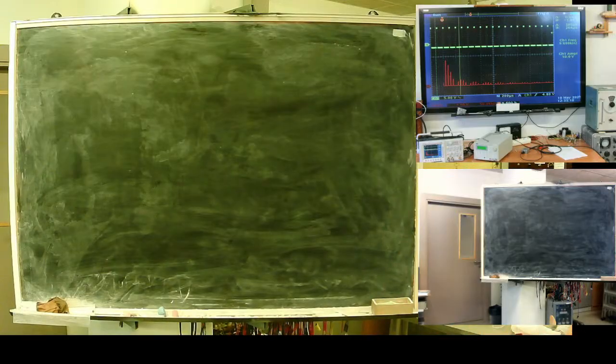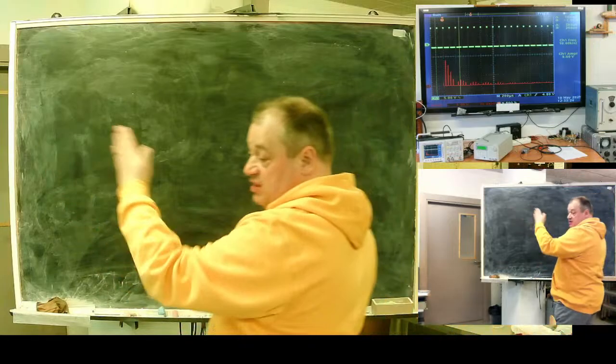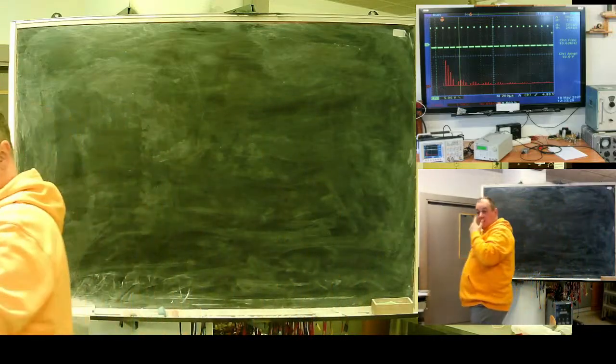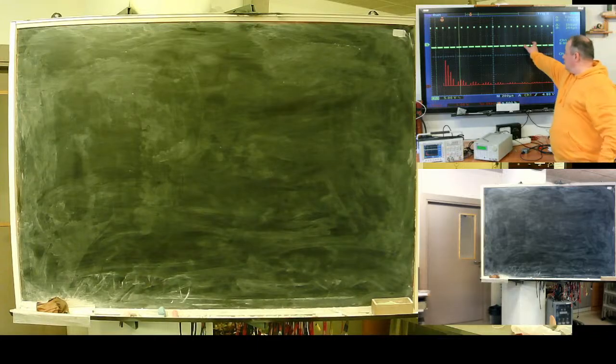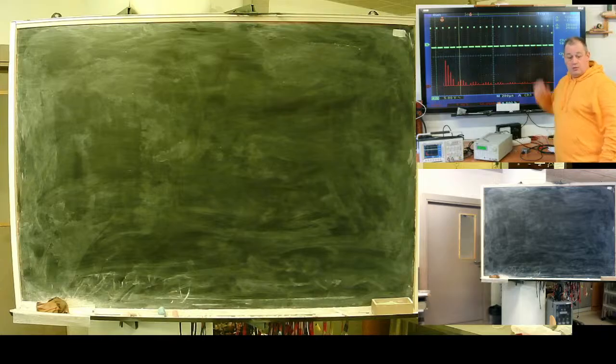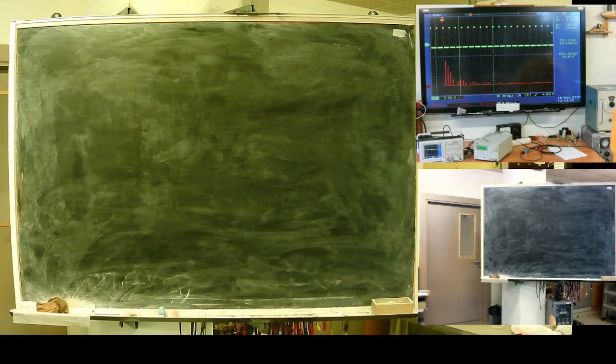In general, what can I use? I can use pulse amplitude to encode something. I can use phase shift, which will be analogous to angle modulation. Or I can change pulse frequency, which will be analogous to frequency modulation, a very popular technique in the car industry. Or I can use duty cycle to put some info inside.